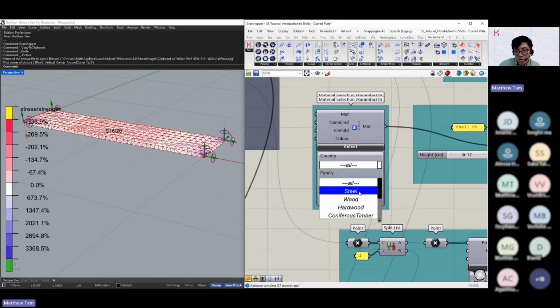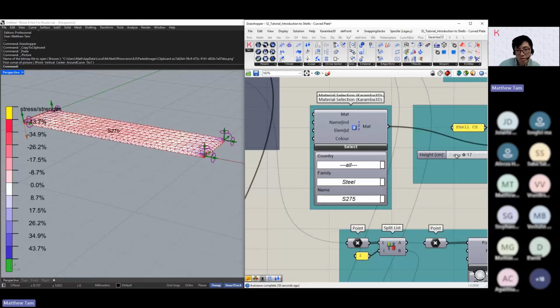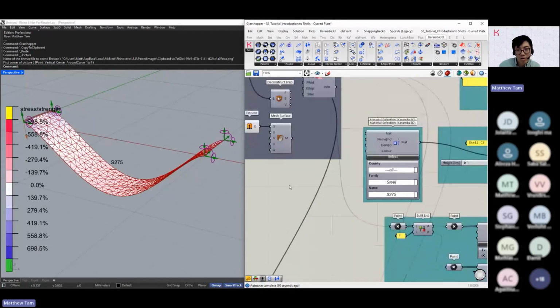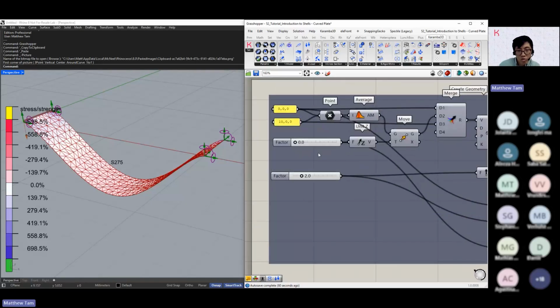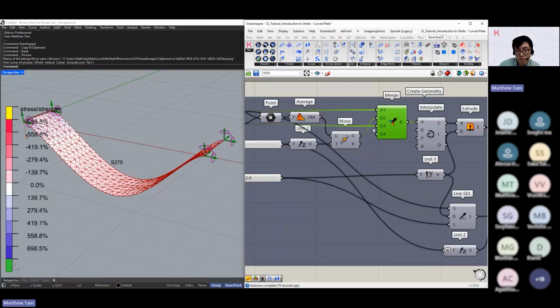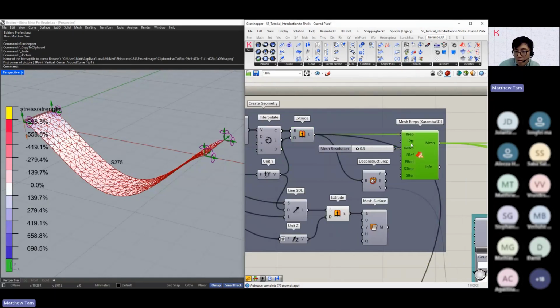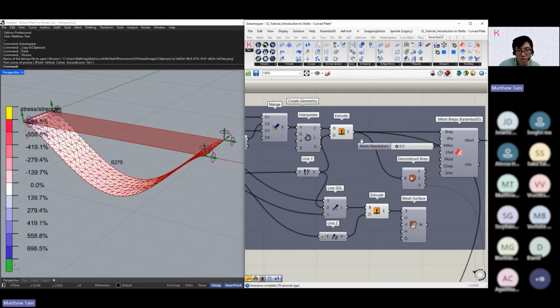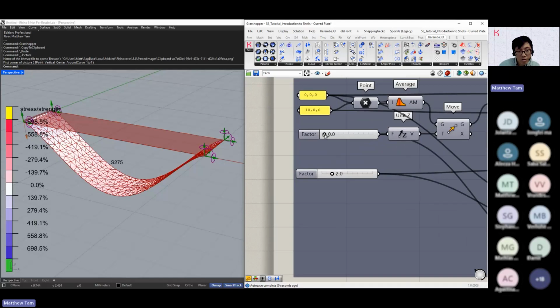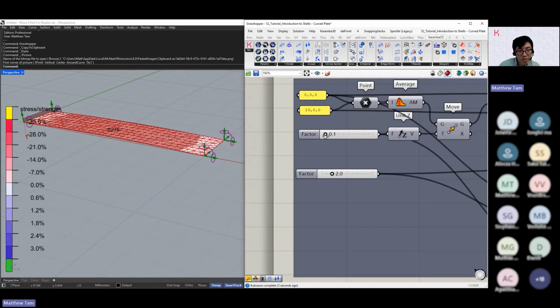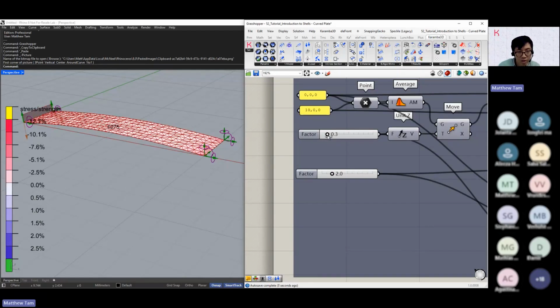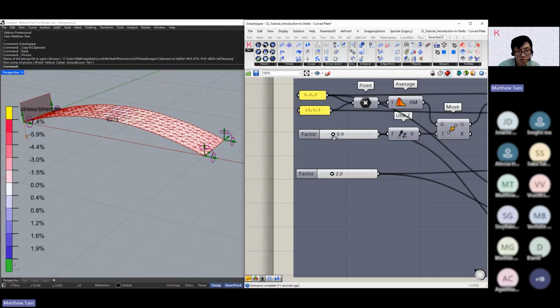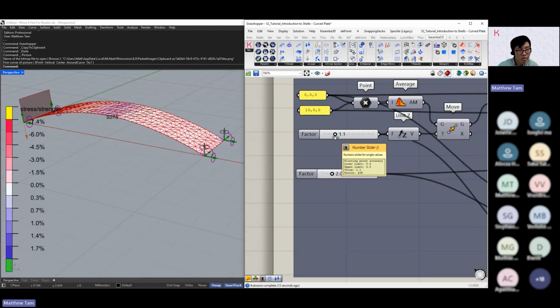I want to now go back to the original steel 1 centimeter. And let's go and change also our initial starting geometry. And so here we're starting with the flat plate, right? And we're, for example, visualizing the gravity load case. But if we now, for example, start to add a tiny bit of curvature, you can see the results already significantly help.